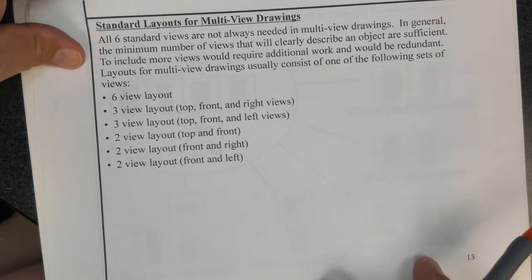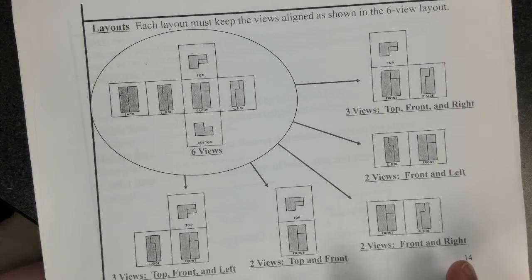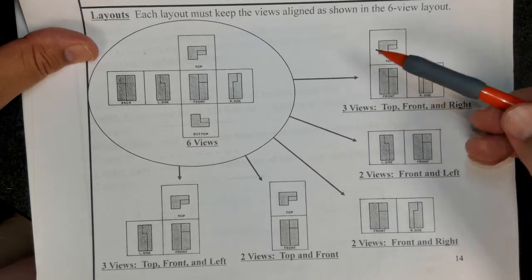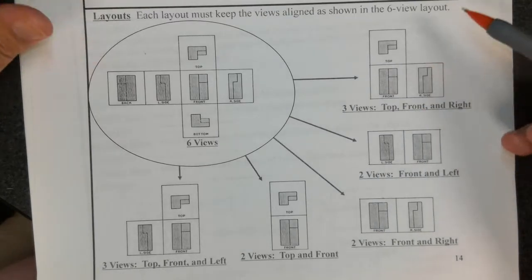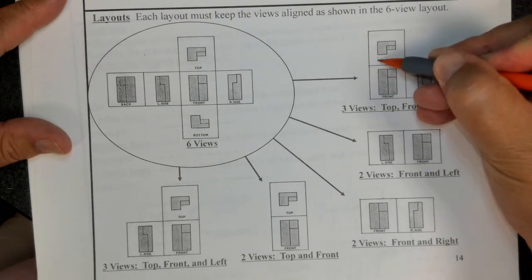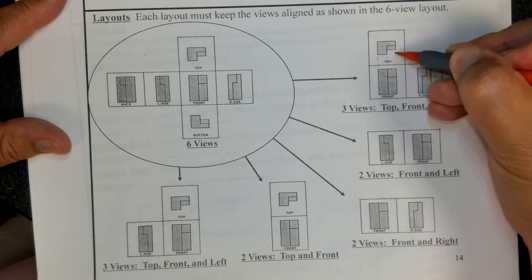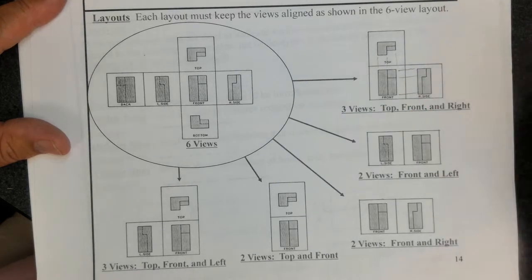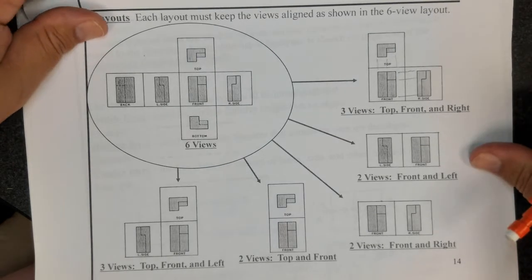All right. So I'm going to skip over these pages right here because it's just showing you various layouts. You always want to keep your views in line with one another. Like, for example, you want these edges to line up. And we're going to talk about this a little bit later when we talk about orthographic projection. Okay?